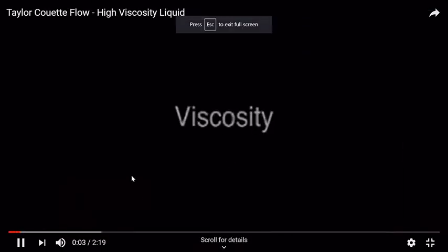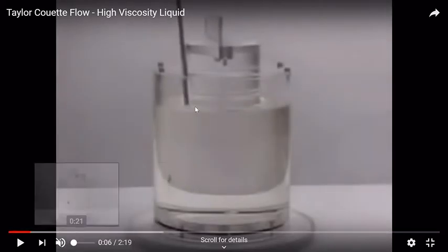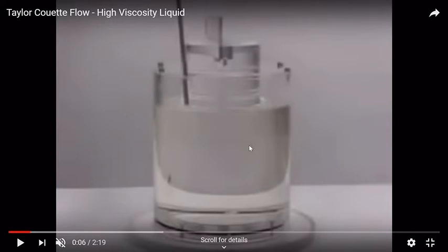Okay. So the setup is basically this: you have two cylinders. There's an outer cylinder and there's an inner cylinder, and there's fluid in between. And it can be glycerine or something, high viscosity like that, right? And Couette flow is basically what the flow looks like when there's relative rotation between the two cylinders. Is the setup clear? Both might be rotating, or only one is rotating. The fluid doesn't care. It just cares about relative rotation.